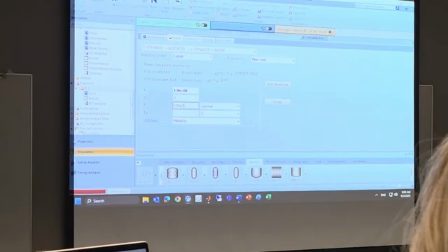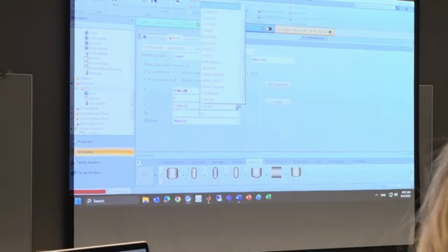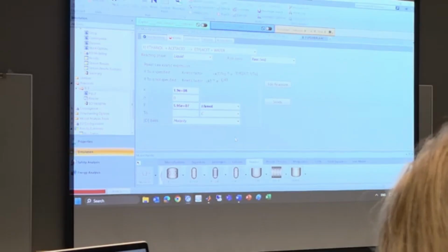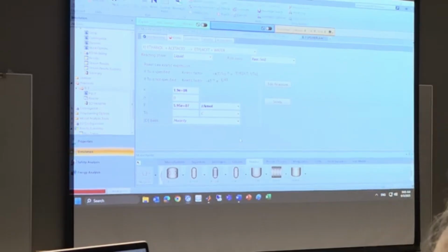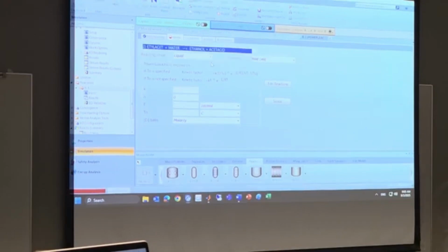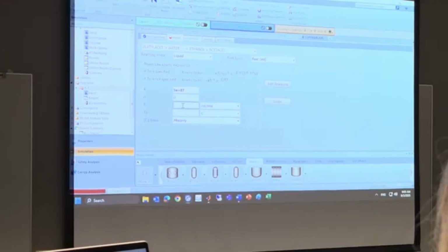The unit is joule per kilomole, so pay attention to the unit. Because we have two reactions, you click the drop-down arrow for the second reaction, K is 5 e to the 7, and the activation energy is 5.95 e to the 7 joule per kilomole.